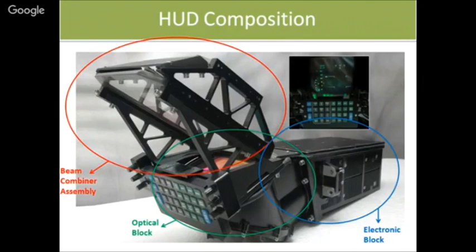Then there is an optical block. Basically, the work of the optical block is to navigate the image which is being displayed onto the CRT front, plus make it collimated, so that when it comes out of the exit lens, which is something which you can see.